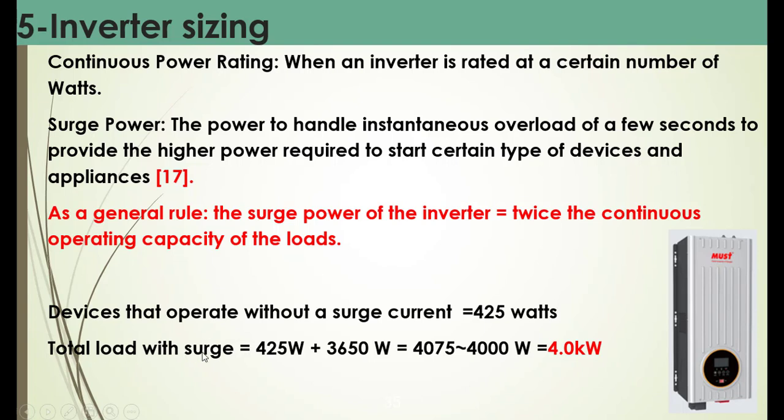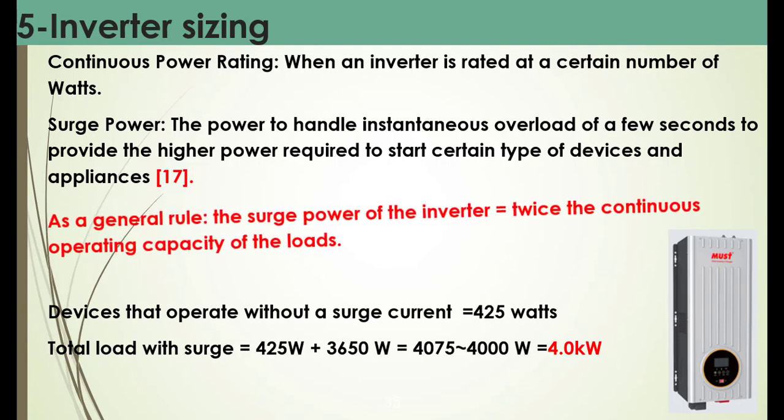So the total load with surge will be 425 watts plus 3605 watts, and this is approximately 4 kilowatt, the capacity of the inverter that we require for the safe operation of the appliances in this design case.